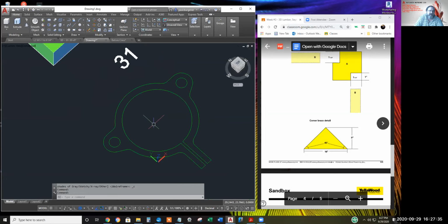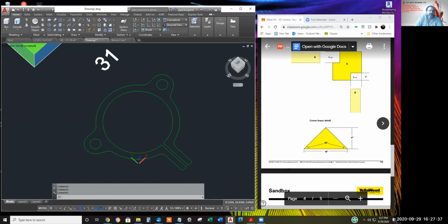Quickly doing the exact same procedure for item number 31 here. Again, the hard part is drawing all these lines and arcs in 2 dimensions. After that, it's pretty easy. Just p-edit, select one. Yes, I want to convert it into a polyline. Invoke the join option by any of the methods we learned in introductory to invoke options.